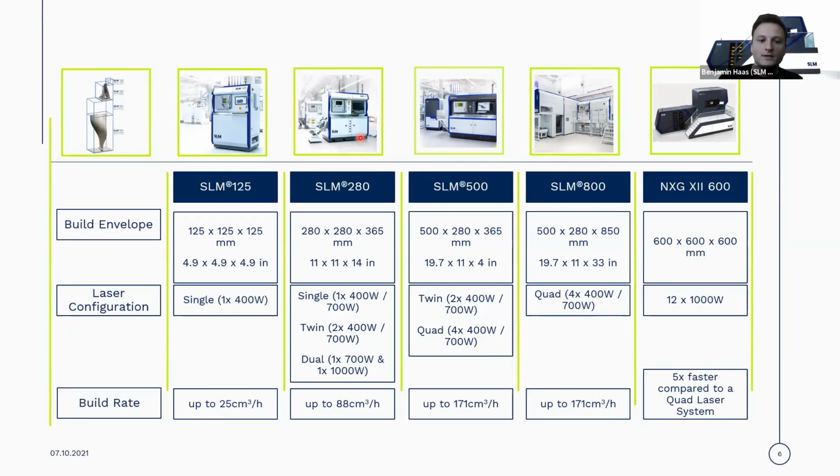In the end, we had to CT scan the entire part, not just a section that is ground and polished, to identify pores. We built this part without any supports with FreeFloat. Overall, the whole part still achieved 99.99% density, so we didn't see any larger pores or porosity.